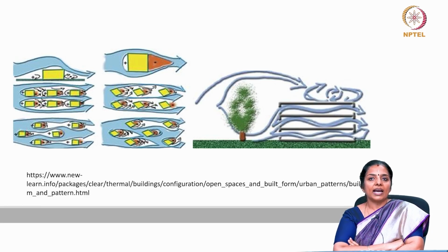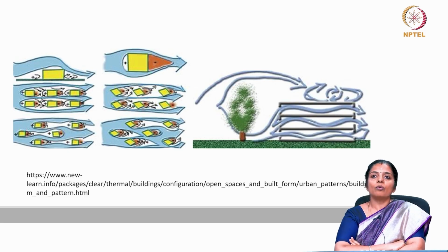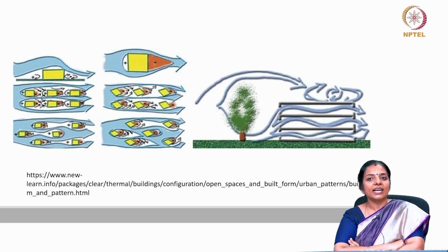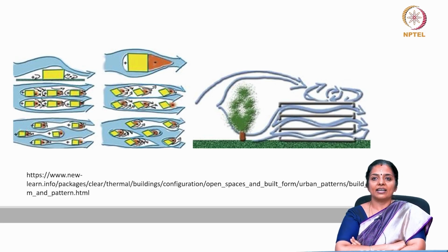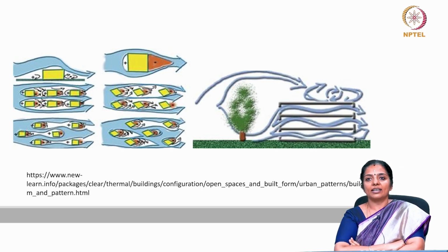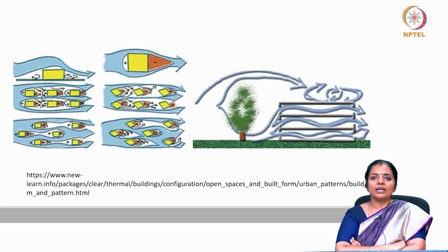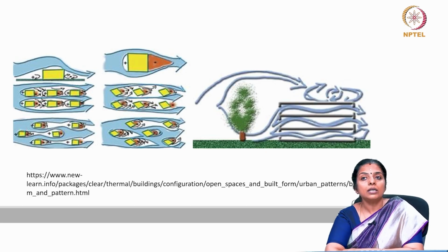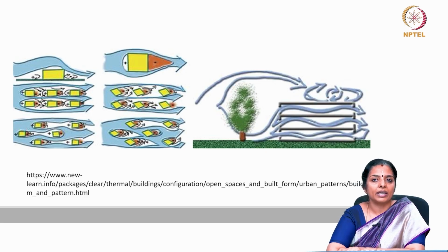The regional air currents flow mainly over the top of the buildings, while in between the buildings a secondary airflow pattern is created as a result of the friction between the upper air currents and the building. This may be desirable in certain climatic conditions like cold winters or hot summers, when winds are to be avoided, but undesirable in warm humid climate when ventilation is required.